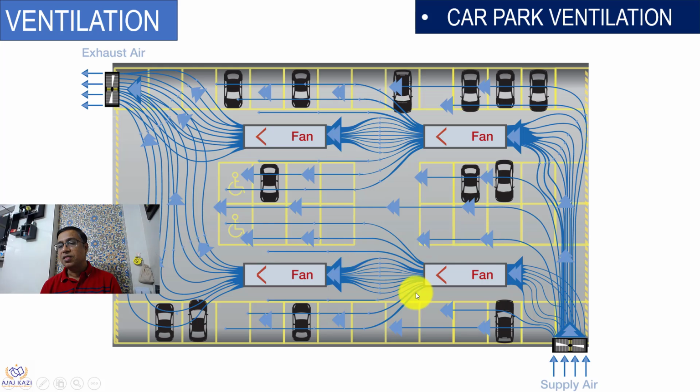You can see the pressure comes in. These fans are displacement type fans. They take air in at one end, go to the other side, and finally it gets exhausted out. So they are actually designed for dual speed, or they are controlled by VFD, so that they can adjust the speed of the fan so that air quantity can be increased or decreased.